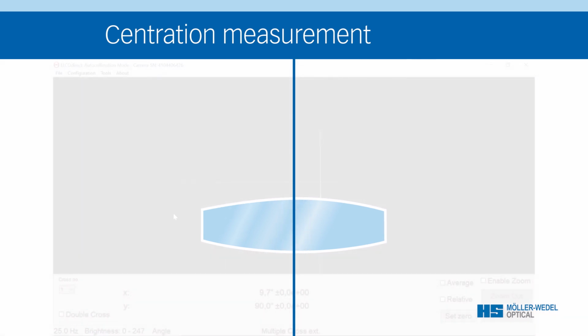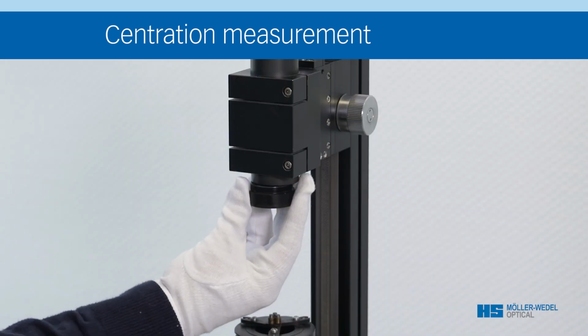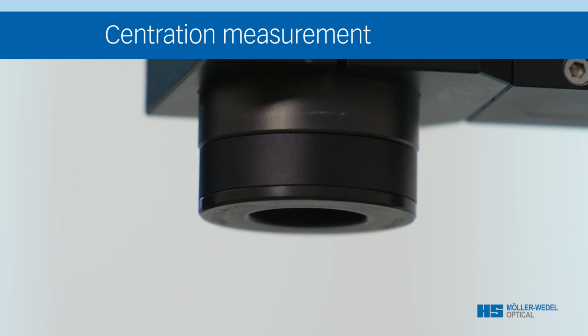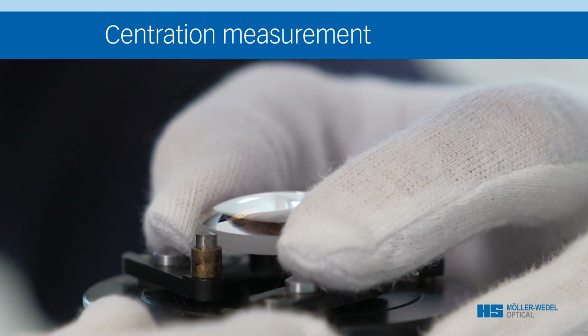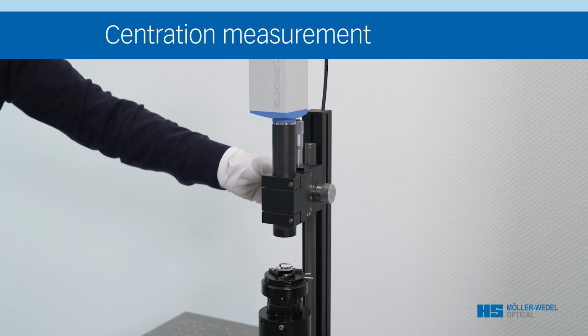Centration measurement of spherical surfaces. The ElcoDirect software is switched to its centration mode. The program window closes once and then opens again. For the centration measurement of spherical surfaces, an attachment achromat is screwed in front of the Elcomat Direct N in order to focus the collimated light beam. The lens is mounted so that it can rotate. The autocollimator is moved until the center of the radius of the surface to be measured is in the focal plane of the autocollimator.